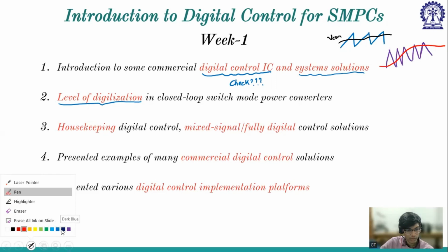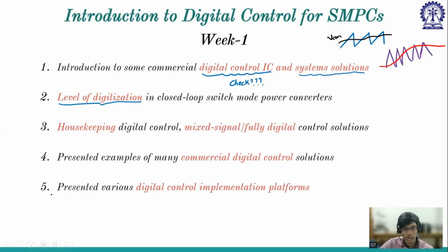Okay, sir, but these modes you are saying, like CMC or VMC, I am thinking that they are restricted to DC-DC. No, no, no, I don't think so. In PFC also they use current mode control and voltage mode control. In DC-DC, the current is triangular, but in the case of AC, it will be sine. So there the reference itself is also changing.